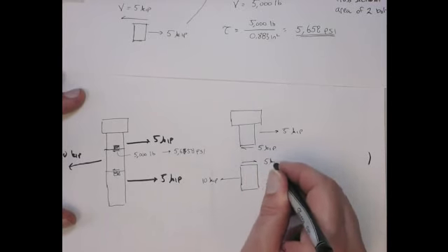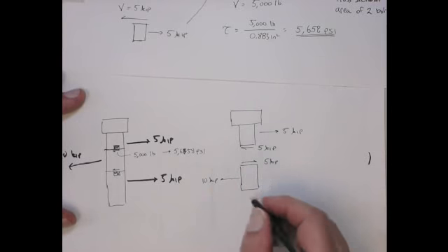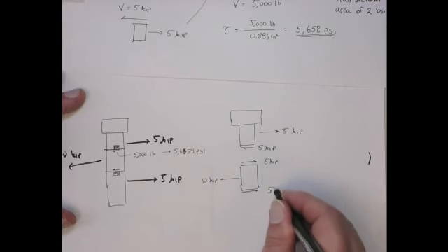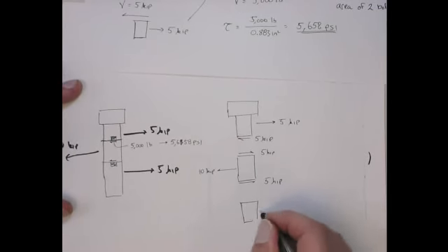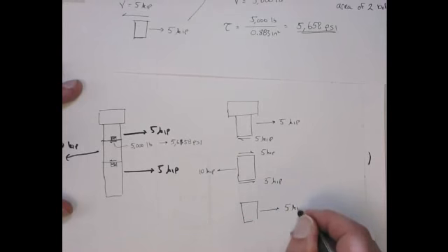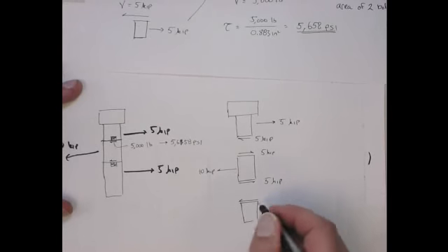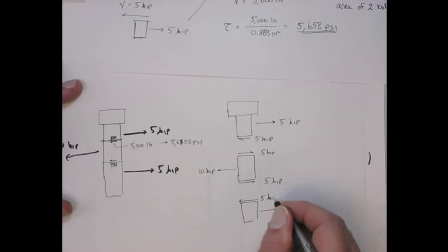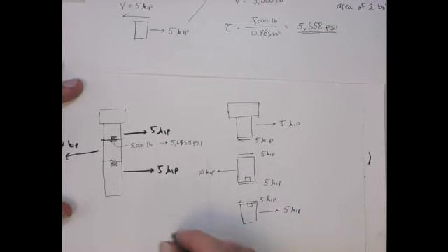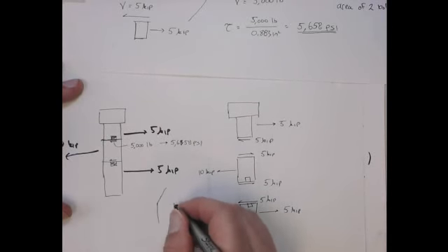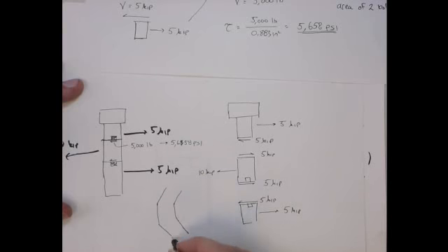Equal and opposite direction because that's the section. 5 kip here. And then the bottom part of the bolt, here's the shear force, 5 kip. So that's the way the bolt is going to see the shear. So it's going to kind of do something like this. I'm kind of exaggerating the deformation of the bolt.